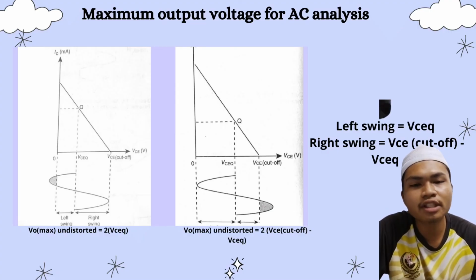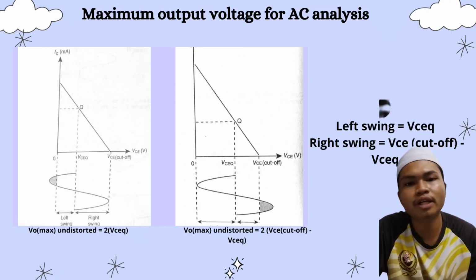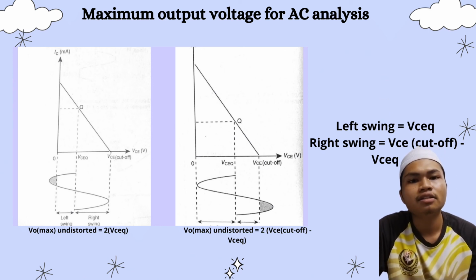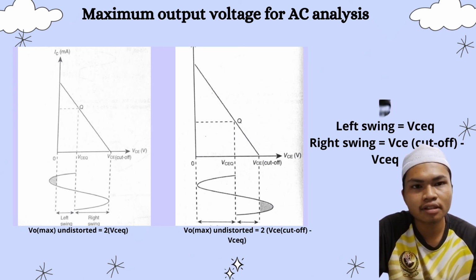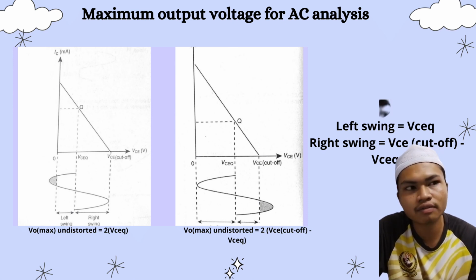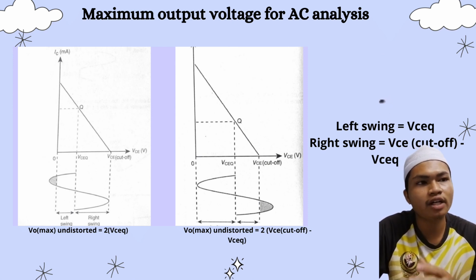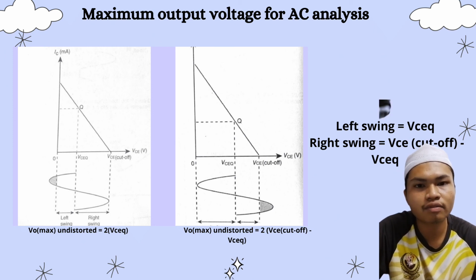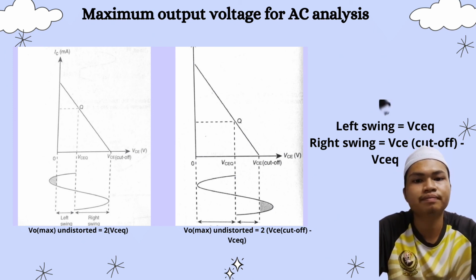Here, I want to present the maximum output voltage from AC analysis. So here you can see two pictures. The left one is VCEQ, and the right one is VCE cut off minus VCEQ.